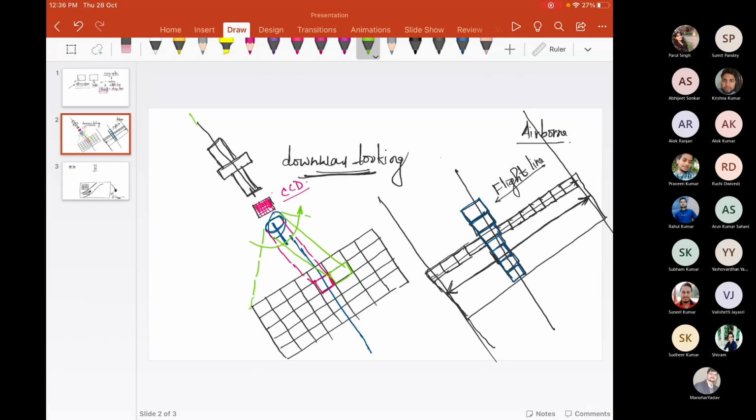So in this way, the ground resolution cells which are confined within the two extremes, leftward and rightward, by providing the rotation to the optics with reference to time, what happens? Energy from different ground resolution cells which are connected across the flight line direction is collected. They are required. But is this the architecture?